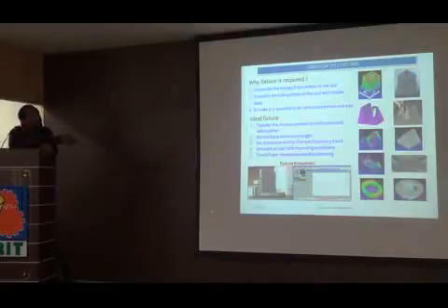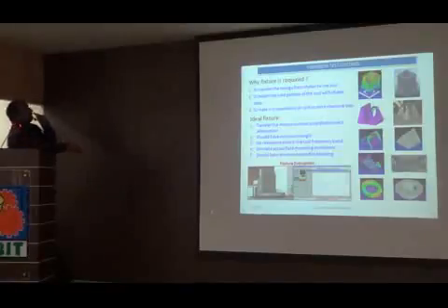And its requirements, like ideal fixture requirements: it should have very little weight and very high stiffness. Ideally it would be zero mass, but that is not possible, and very high stiffness. So that means it should have optimum stiffness, and there should be no resonances in the frequency band, and it should have good damping because it needs to be controlled, because we are controlling the vibration inputs.